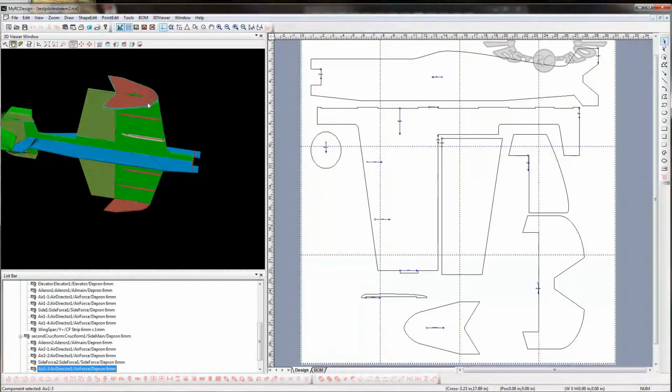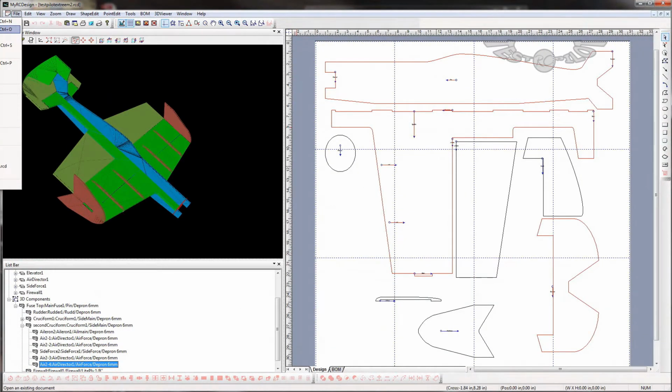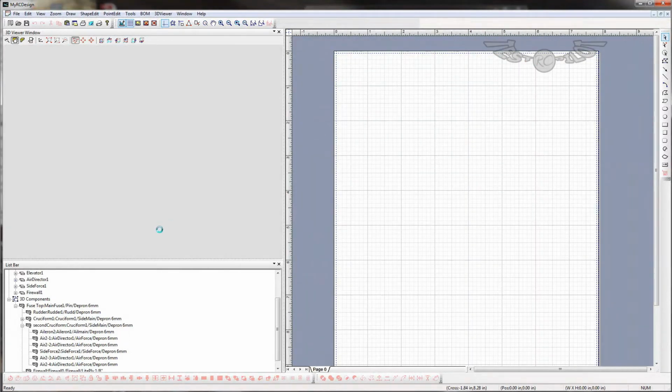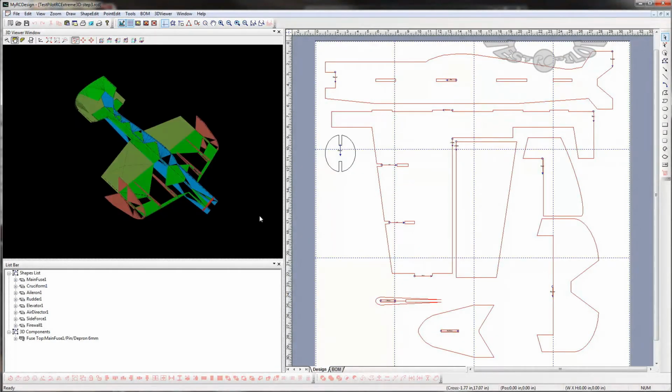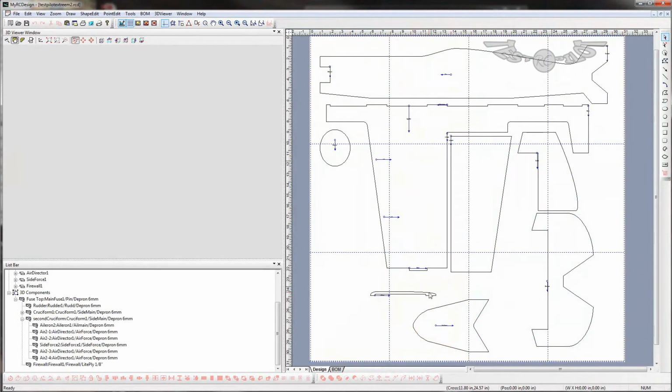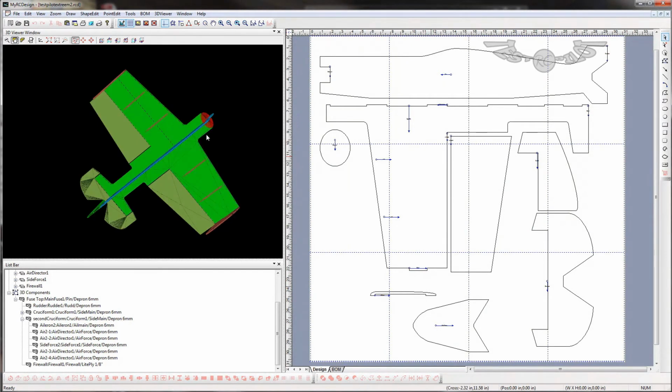They're actually two halves. I'll show you the original design for those air directors. The Extreme 3D Step 3. Okay. Plane looks pretty much the same, except I had cut a lot of holes in it to show where joints were going to be and all that. And it was originally one piece with these really thin lines going in. And the laser cutter that they use can't actually utilize thin lines because it will just vaporize the foam, and you're going to end up with something really ugly. So we managed to accomplish the same thing by making it two pieces and not having anything super narrow.